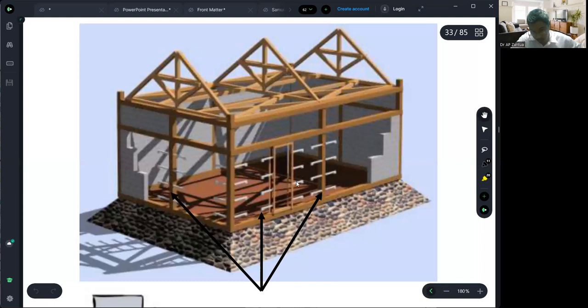This white here are the connectors for the door frame and wall connection, so that the door frame and the wall are connected to each other and move at the same time. Meaning if the wall moves, the door moves at the same time, so they will not be damaged. So this wall would extend up to this portion. They are the provision for connection.